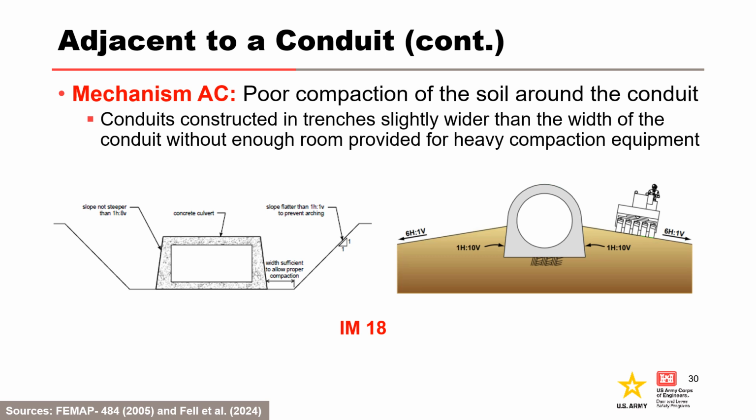Poor practice has little or no width between the culvert and slope, near vertical slope, and vertical side slopes for the culvert, which preclude the use of rollers to compact the fill against the culvert. On the right are good details for cast in situ or precast round concrete culverts, showing a rounded top, which is better for localized stresses, and sloping sides to allow compaction with a roller.